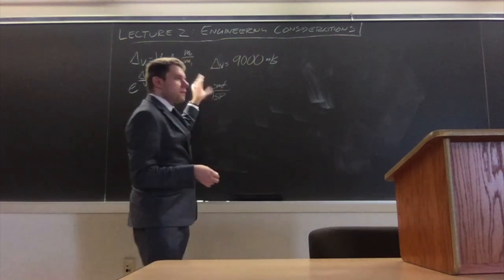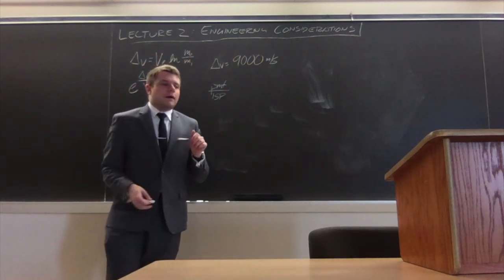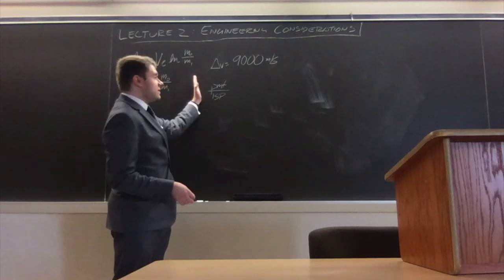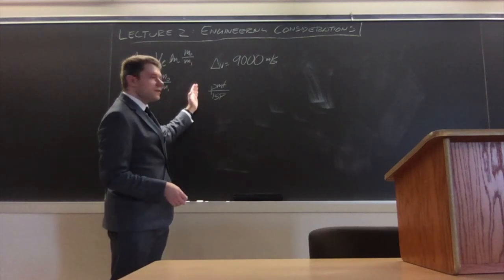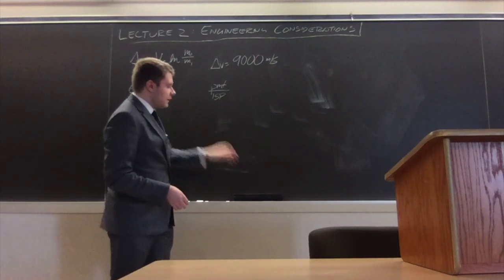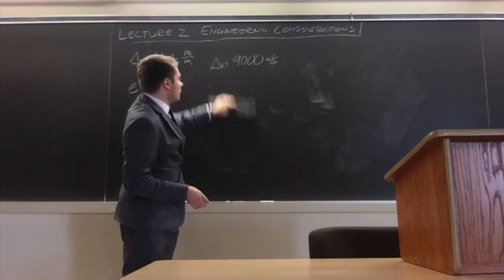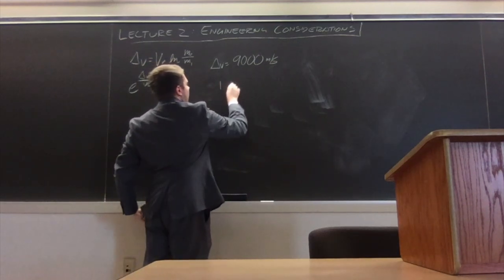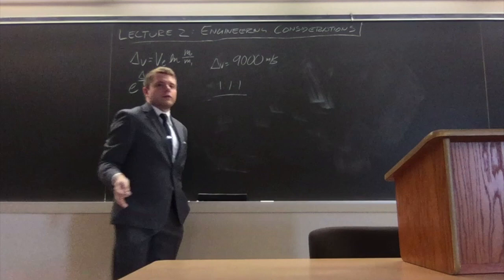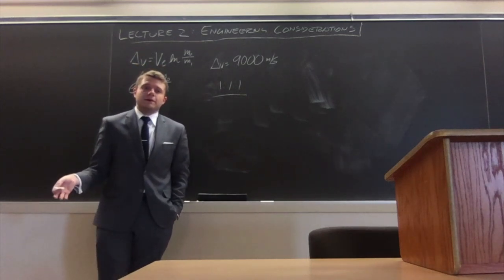So you have to make that consideration. But, big asterisk, you can actually, if you assume that each stage has the same propellant mass fraction and the same specific impulse, effectively treat it as a 1-to-1-to-1 ratio across your entire rocket. In other words, all the stages have the same delta V.